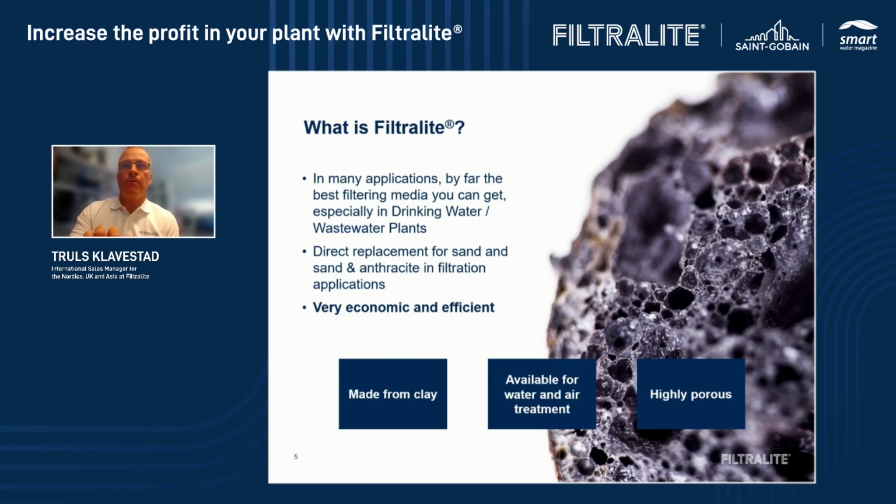Only one thing is important to keep in mind: you need to reduce the speed, or the frequency, of the backwash pump. Because Filtralite is a much lighter material compared to sand, to avoid flushing the material away, you have to reduce the frequency of the backwash pump, which will also give you a benefit in saving energy consumption.